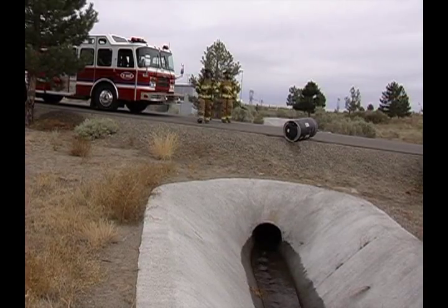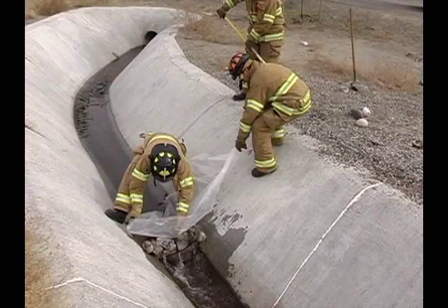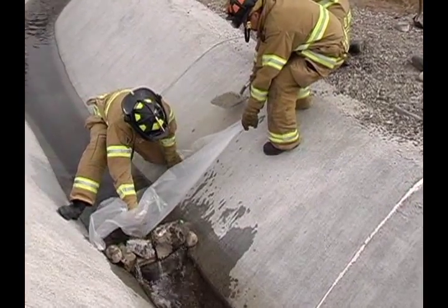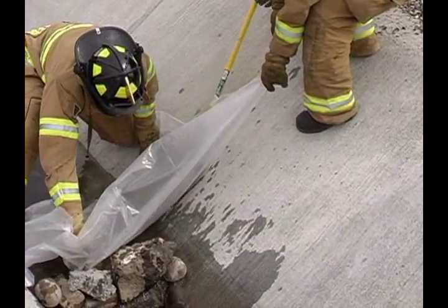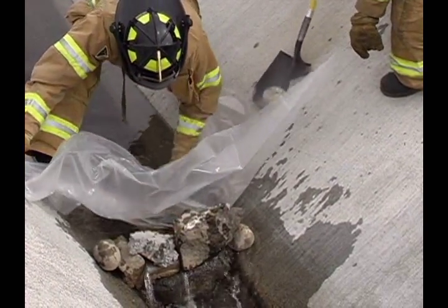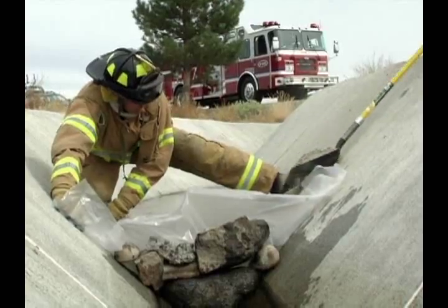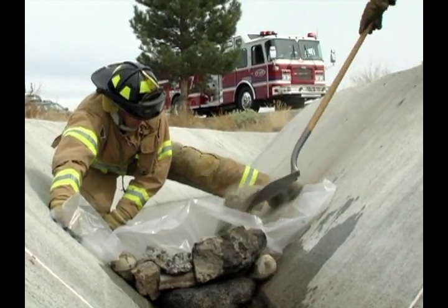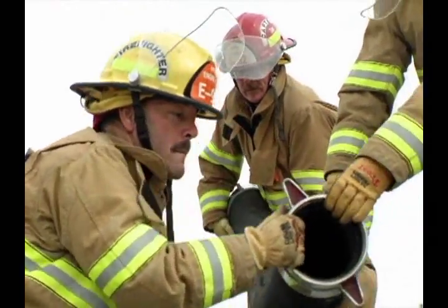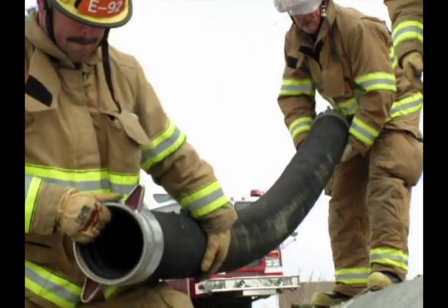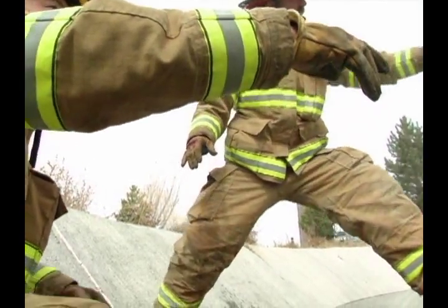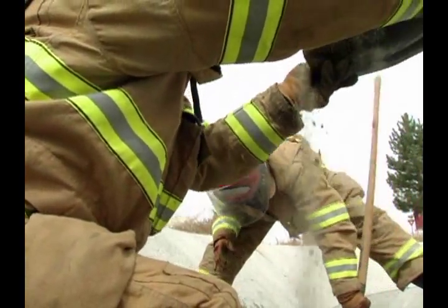At the scene of a spill near a waterway, you may choose to employ diking or damming as a control technique. The purpose of diking and damming is to contain a spill on the ground or within a waterway. The equipment you'll need can include dirt, sand, or rocks. You will also need shovels and pipes to construct overflow and underflow dams. Secondary contamination is a risk you'll need to account for when using these techniques.